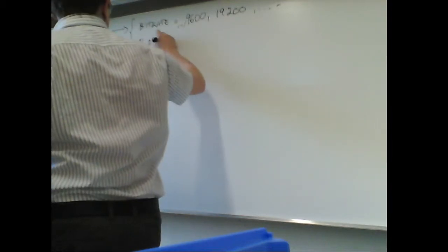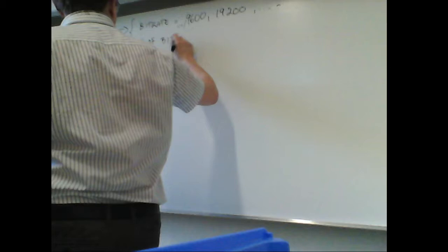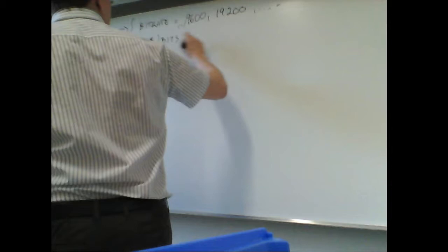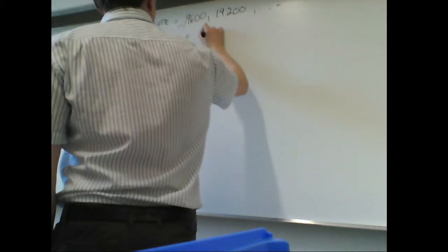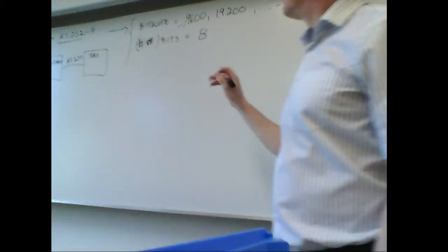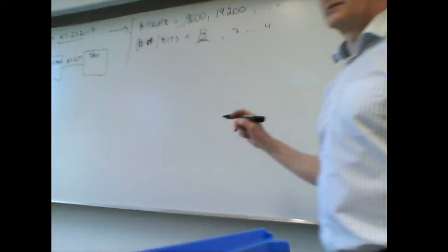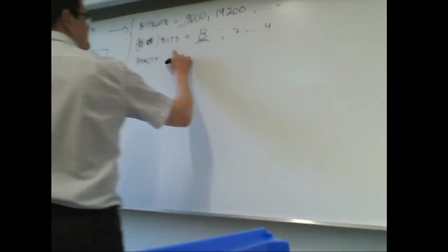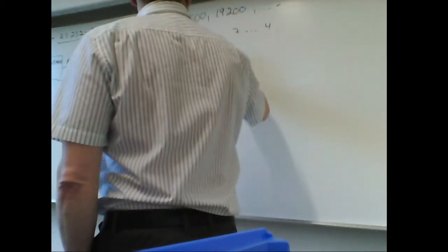Number of bits. Usually, it can be also smaller than that. 8 or 7, depending, but that's most common. Down to 4, actually. Less than 4, it's not allowed. Then parity. No parity is the most common, even parity or odd parity.